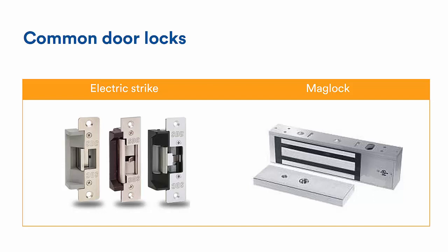Electromagnetic locks consist of an armature and a coil assembly, which become magnetized when electric current passes through them. This magnetic field secures the door and electronically controls when doors are locked and unlocked. Recall that electromagnetic locks are fail-safe by design, meaning that if power goes off, the door will be unlocked. You'd need a battery backup to keep the door secure during a power outage.